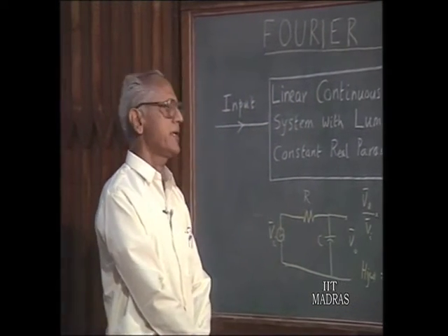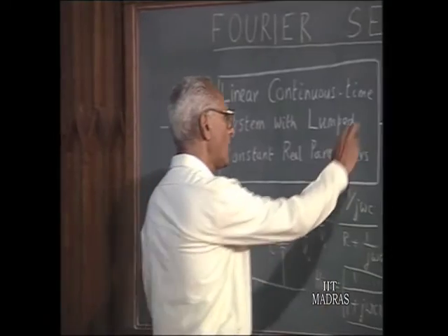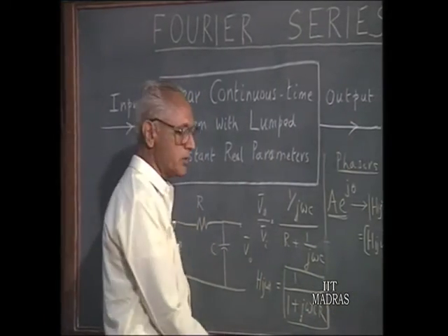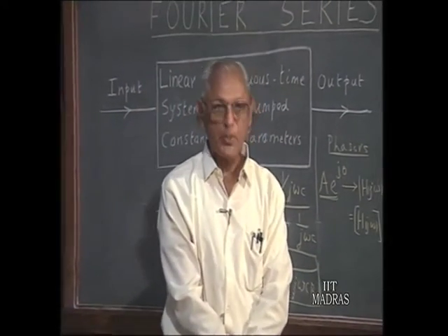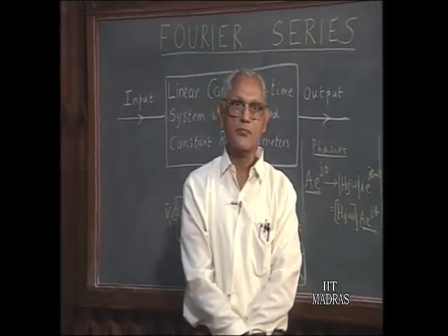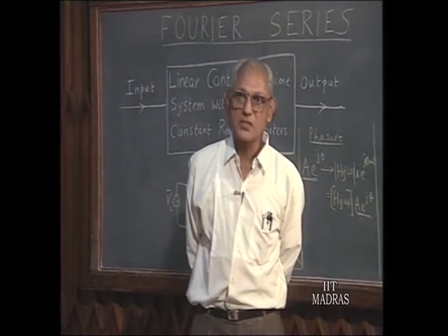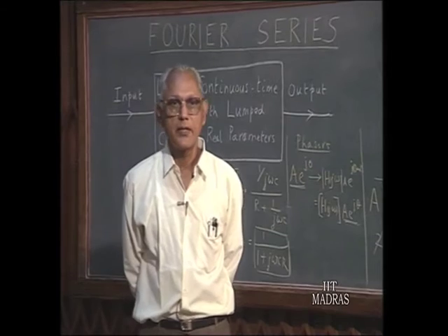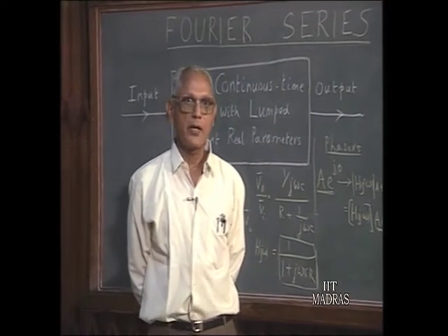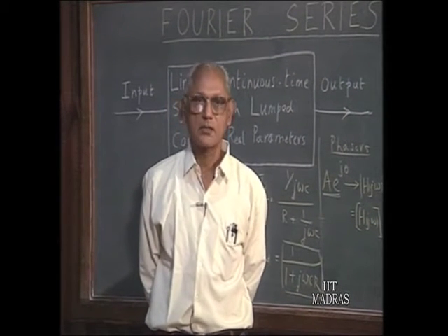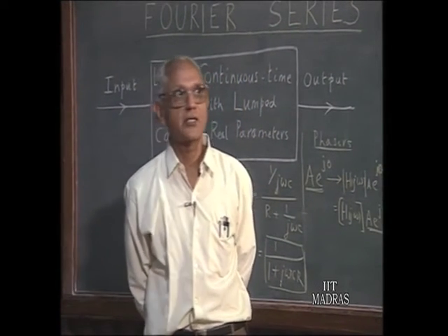Now, we understand here, of course, that when we talk about the output in the entire discussion here, we are talking about the particular integral solution. Suppose you have an input, when we talk about H of s, system function and so on and so forth, normally the output is the particular integral solution. In the case of AC signals, sinusoidal signals, the common systems, the complementary solution gives rise to decaying transients, and therefore the particular integral solution is what remains forever. It is the steady state solution. The complementary solution is a transient process.